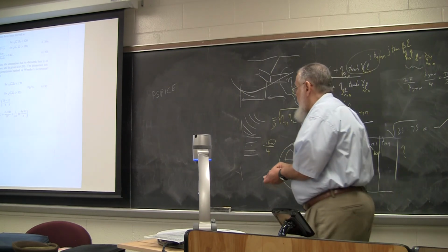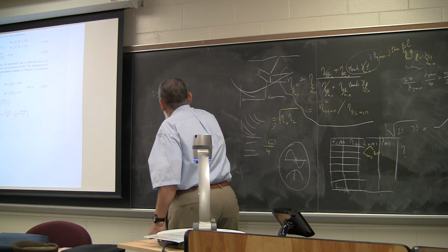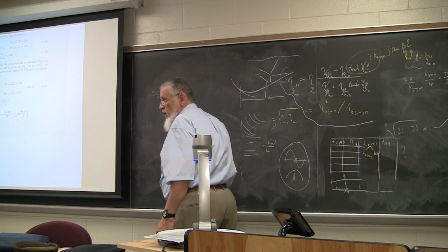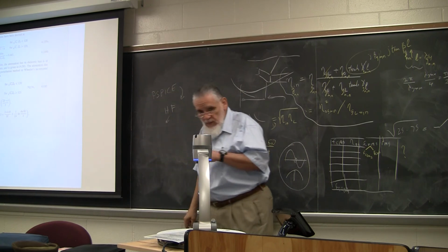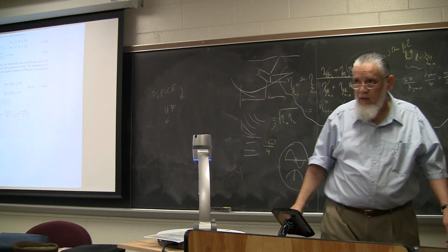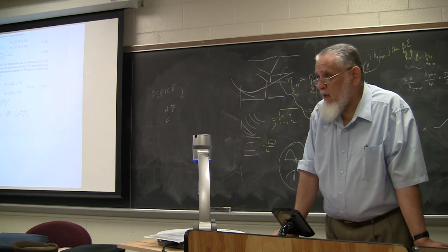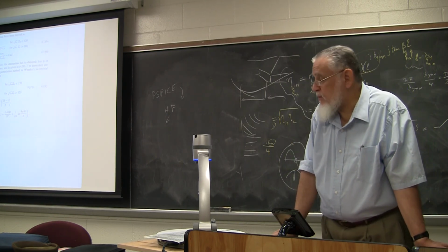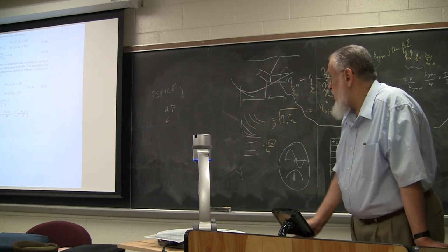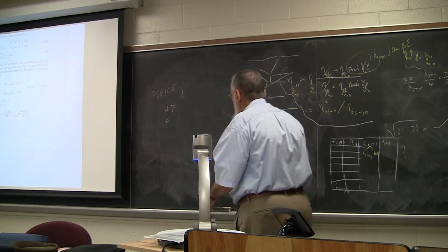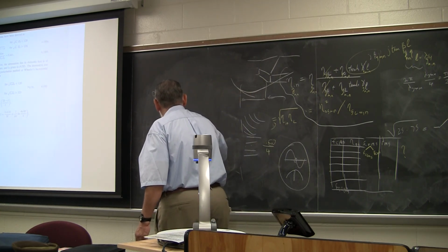Well, there are similar things for high frequency, and there are several packages. One of the famous ones is the Advanced Design System by Agilent. That had many names in the past; I think it's called ADS now. Basically it has those built-in models for different things, so you can put in a strip line, right? And